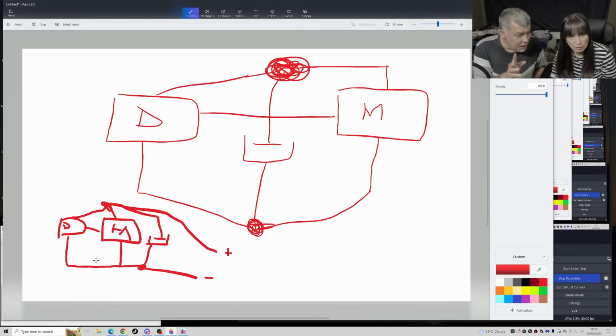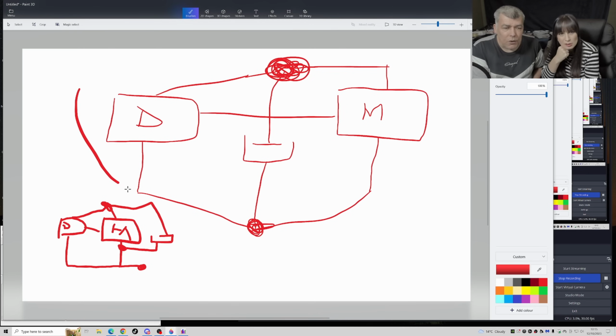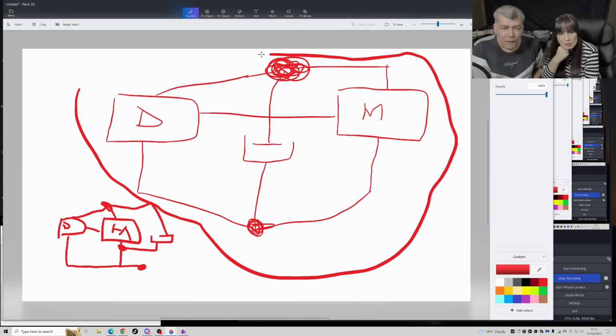You have two ways. Like we spoke, connect the capacitor exactly on the source noise, on the switching MOSFET. So from here is minus, and it's going to the plus exactly here, or you use this schematic to handle the power distribution on your circuit.